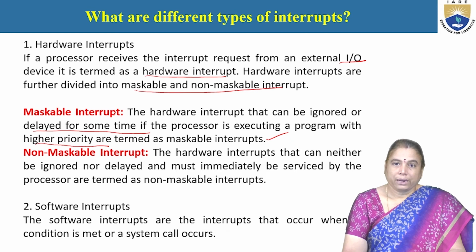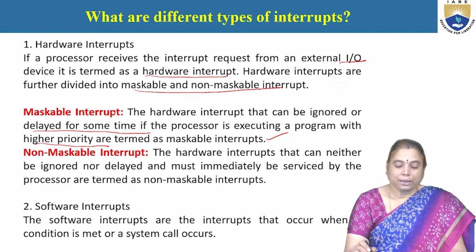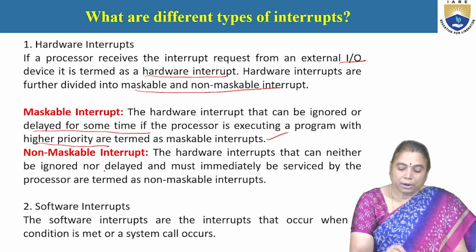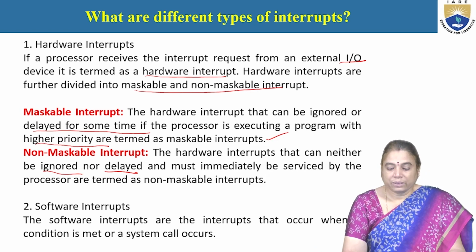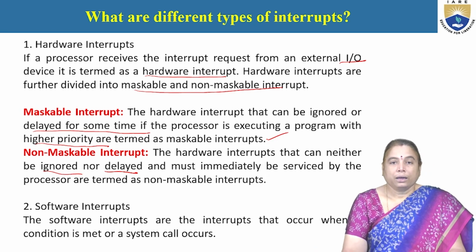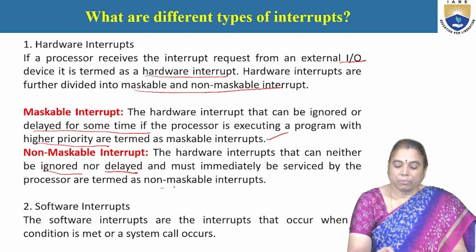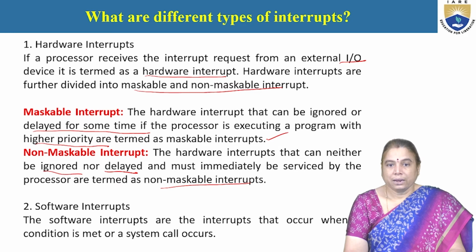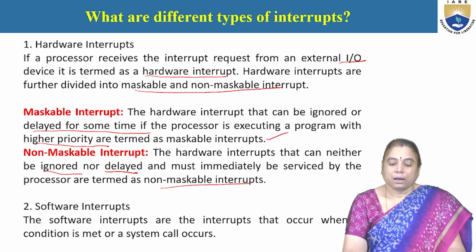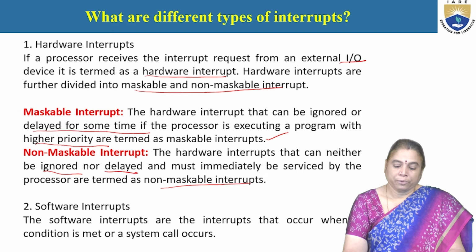The second variety is non-maskable interrupt. The hardware interrupts that can neither be ignored nor delayed, and must immediately be serviced by the processor, are termed as non-maskable interrupt. So, immediate service needed interrupts can be the non-maskable interrupt.